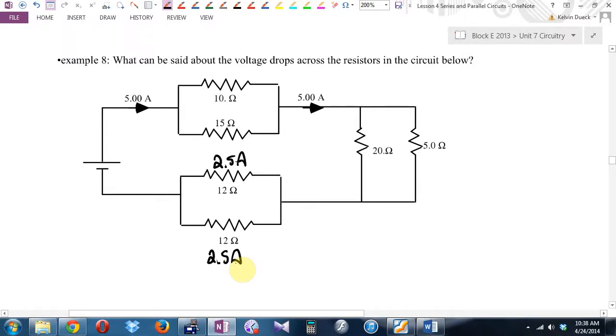Do I know two? Yes. What's the voltage in that top one? Heck, what's the voltage in the bottom one? You lose 30 volts. In fact, Kayvon, I really didn't need to do both of them. Can I shake hands here, because this is downhill, and meet up here? Then you know what? Each of those resistors must be the same height, same voltage drop. Can I shake hands here and meet up here? Yeah. Then what can you tell me about the voltage here and the voltage here? They're the same. If I find one, I'll know the other.